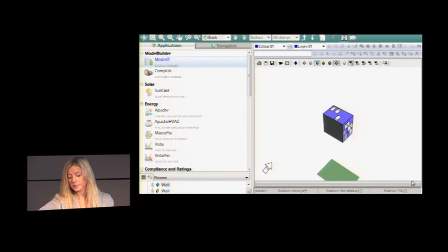But in Revit, since you're going to set your constructions and everything when you go into IES, and the adjacent temperatures, all of that's important. It's just making sure that your model's at 0. Anything that you build below 0 will be below grade inside of IES. So you're just building it the same way as you would build any other room, but below 0 elevation.